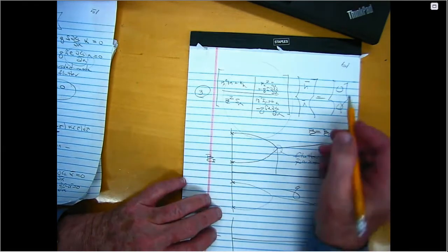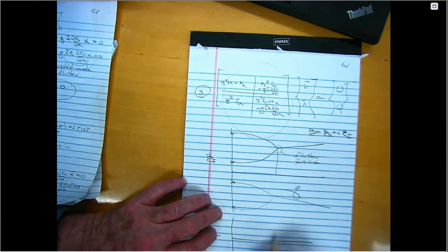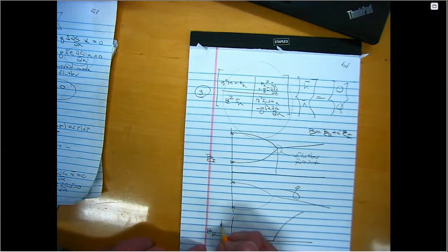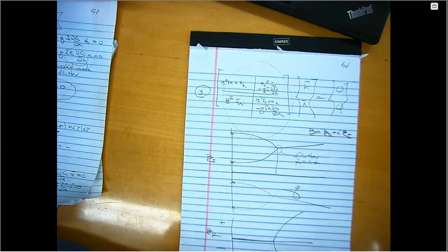The real part, with this simple model, up to this point, the real parts are all 0. There are 4 of them, but they're all 0. And then they split. One goes positive, and one goes negative. Actually, 2 go positive and 2 go negative. Right? It only takes one positive real part to make the system unstable.